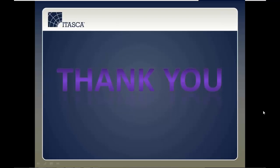That sounds maybe a little bit complicated, but in practice it's very easy, because Rhino easily provides ways to copy completely, extract a face from an existing solid, extract another face from an existing solid, and basically create a solid sandwiched between the two faces. So this becomes a moot point when you're working with Rhino. But yes, it's your responsibility as the creator of the block layout to make sure that these blocks share the same corners, edges and faces.